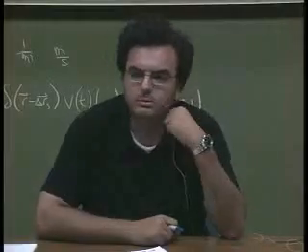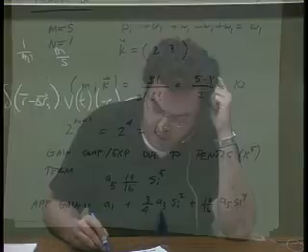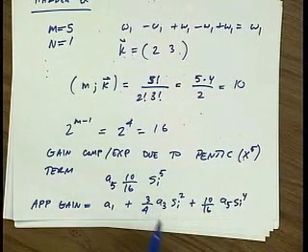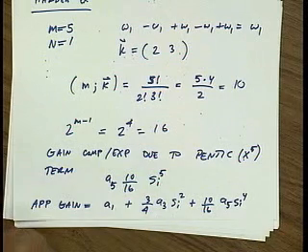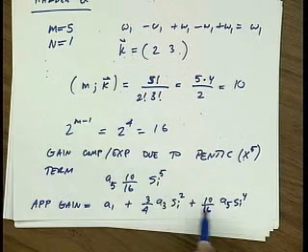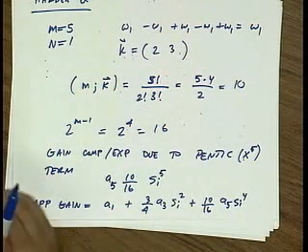Can you use the mic? How would you get a minus term in this if you were to get gain compression? So the sign of A3 and A5 are not known, right? They could be negative. Good point. You'll notice that once you know the sign, the gain compression or expansion is independent of the signal level because you're taking even powers.